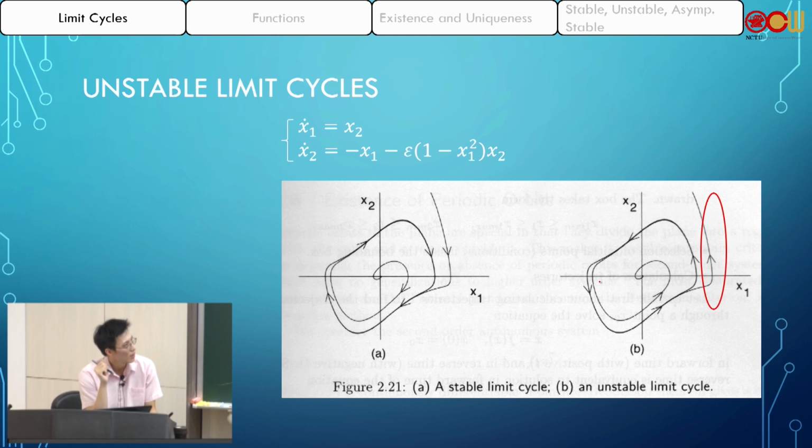So the previous case is stable, right? Now, what is unstable? This is unstable on the right-hand side. So, for example, if your initial condition is here, it can go outwards and diverge, right? So it's unstable. Even though if you start from inside, it might converge to the origin, from some other location, it can go unstable. So you cannot say it's stable. You can only conclude it's unstable. Stable means, in general, okay? No matter where you are, you should guarantee that it will be stable.